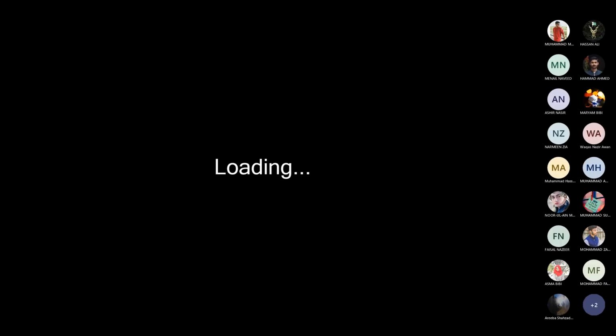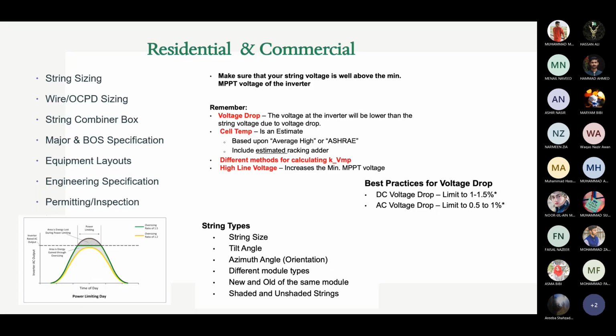In the inverter, at peak time, there are clipping losses. We cannot generate power from the clipping, so this power is lost in the inverter as clipping loss. Based on the site location, we need to properly select the DC power of the solar PV modules compared with the inverter rating, so we have to minimize the clipping losses from the inverter.